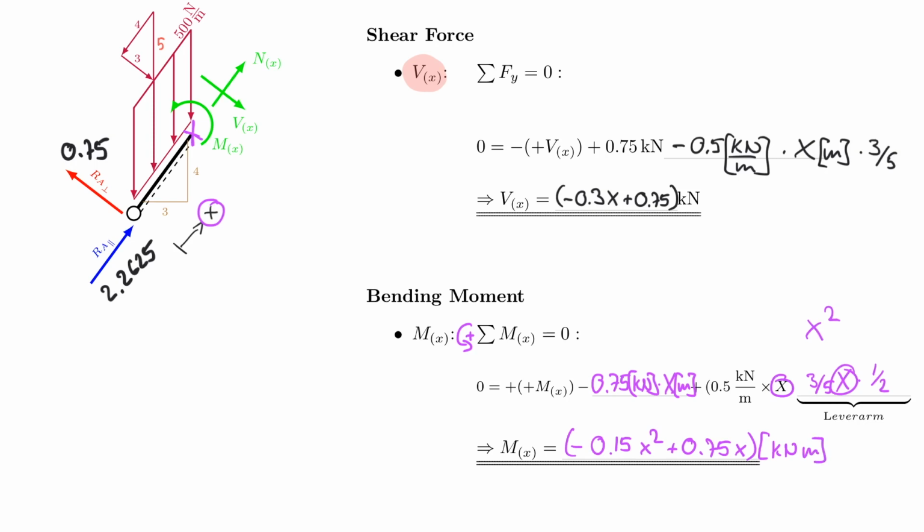So number one, if I plug in 0 into this equation, then my value has to be 0 because there's a hinge here. I mean, this is only a hint that I give my students, but ultimately there's just a support there. And so the support reactions have no lever arm yet. Therefore, if you plug 0 in, the moment must be 0 at this location. And that is true if I plug this in. Also, what's true is that the shear force is the derivative of the moment. And what have I done now?